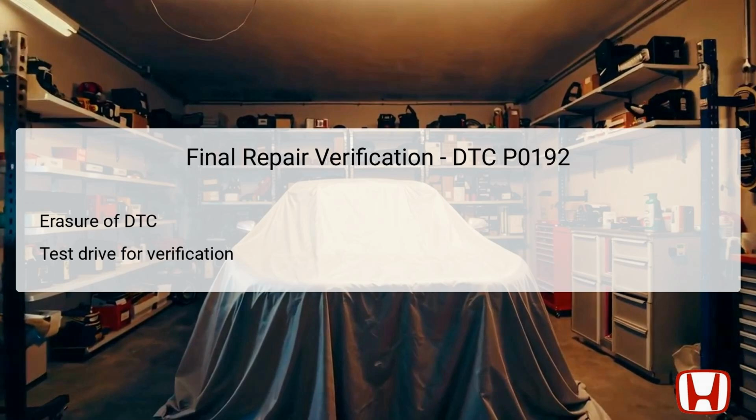Post-repair verification is a vital part of the diagnosis and repair process for DTC P0192. Once repairs have been completed, it is essential to erase the DTC from the PCM. This can be accomplished using a scan tool, which allows the technician to clear any stored fault codes and reset the system. Following the clearing of codes, a test drive of the vehicle should be conducted to ensure that no codes reappear and that all systems are functioning as intended.